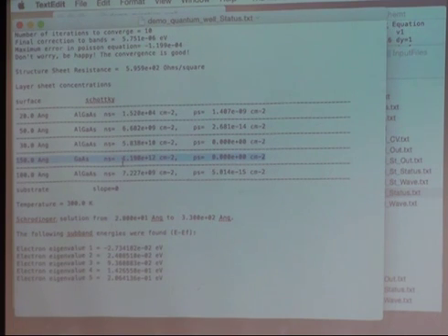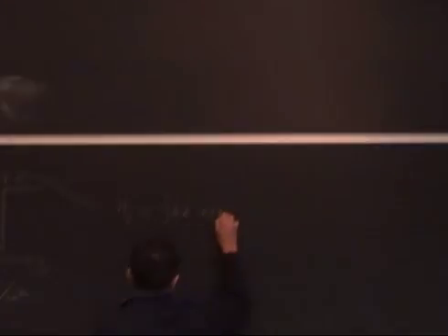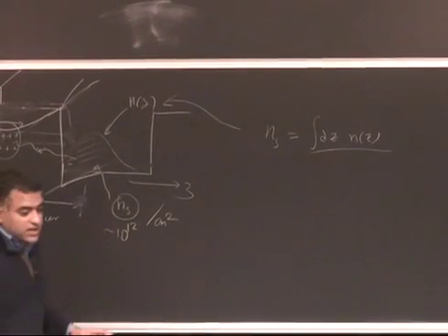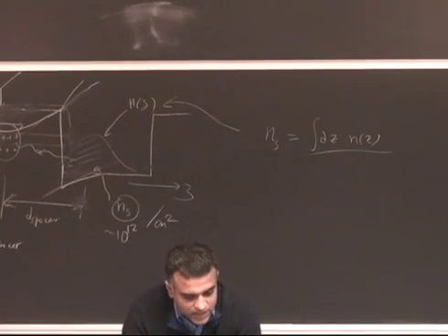The sheets are like this way in the diagram. So this is n of z, where z is this direction, but really this is a planar structure. You have the whole thing going in, and so the xy plane is the sheet. What it's telling us is the sheet density, which we can call n sub s, essentially just the integral dz of n of z. That's all.